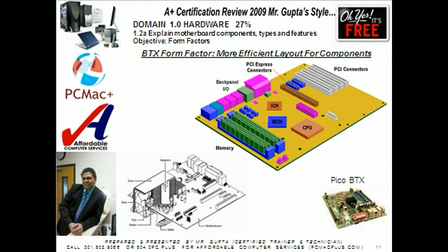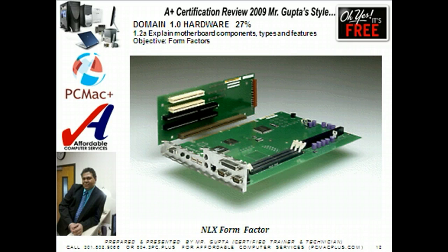The BTX motherboards are designed to be available in 4 different sizes: BTX, similar to full-size ATX, Micro BTX, and finally the Nano BTX and Pico BTX for small form factor computers. The difference between the last two is that the Nano BTX offers 2 expansion card slots versus 1 for Pico BTX.